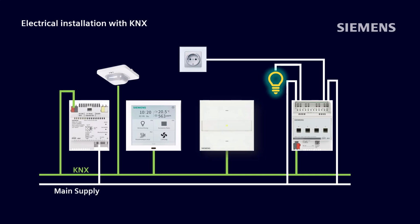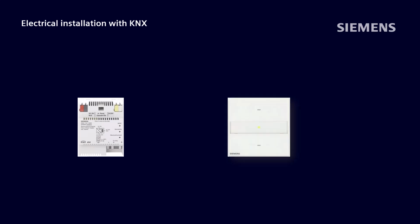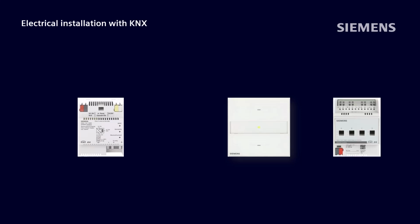Let's now take a step-by-step look at which components are needed and how data transmission works. First of all, we need a KNX power supply to supply the KNX devices with the necessary energy. Depending on the number of components in a KNX line, a supply with the appropriate output current is required. Furthermore, we need a sensor or an operating device to turn the light on and off, and finally an actuator or dimmer with outputs to control a consumer, such as a bulb or a socket.